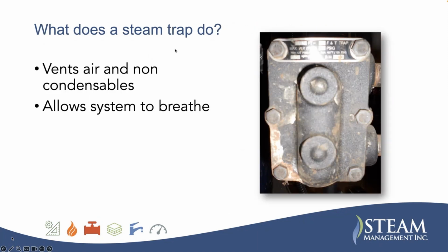What does a steam trap do? It vents air and non-condensables, but more importantly, it allows the system to breathe. So it vents air out when it's steaming, and it allows air back in when the steam is condensing.